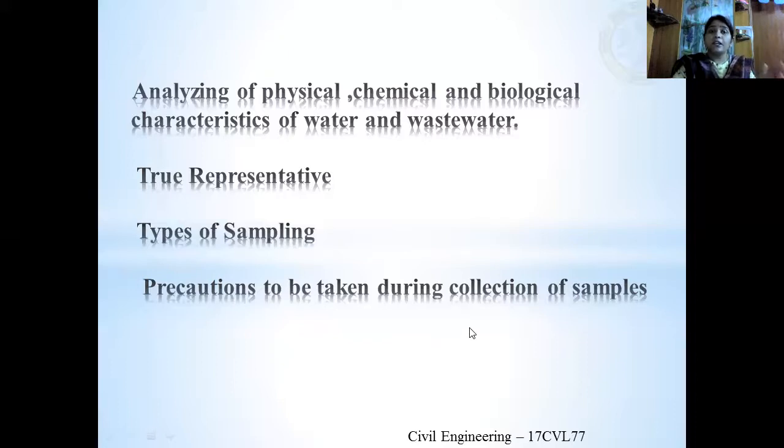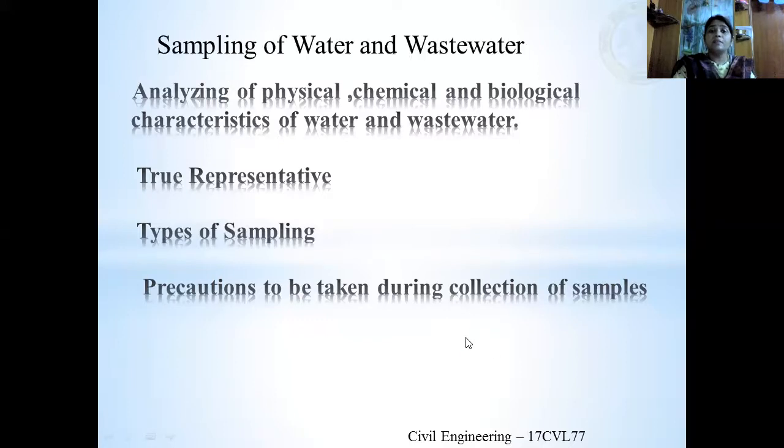Sometimes the collection and the analysis may be delayed. At such a time, we need to add certain preservatives so that any chemical reaction or biological reaction won't take place and the sample is not going to be disturbed, and we will have a true representative, and hence finally the values are going to be determined, and the treatment is going to be decided, what treatment has to be given.